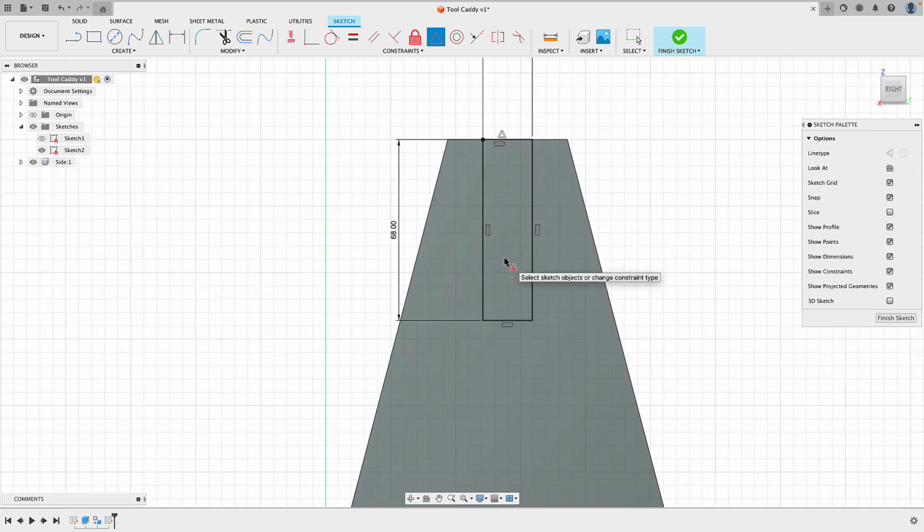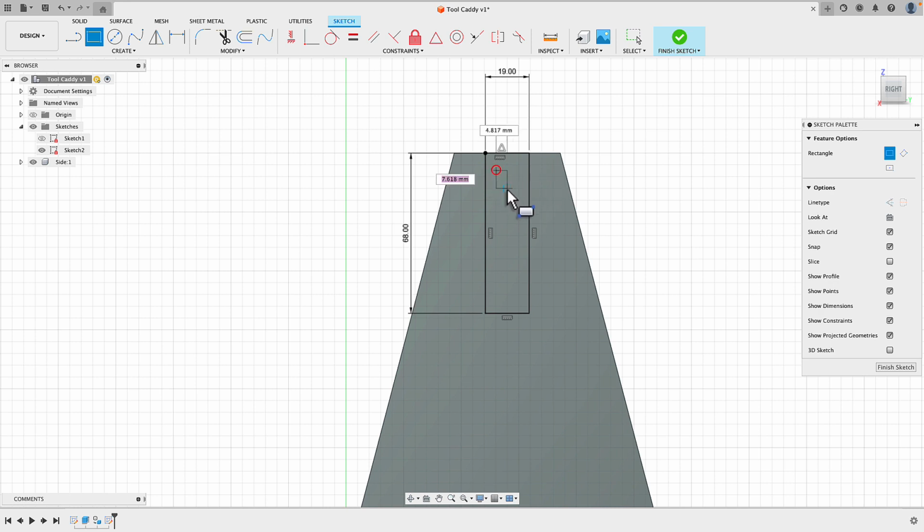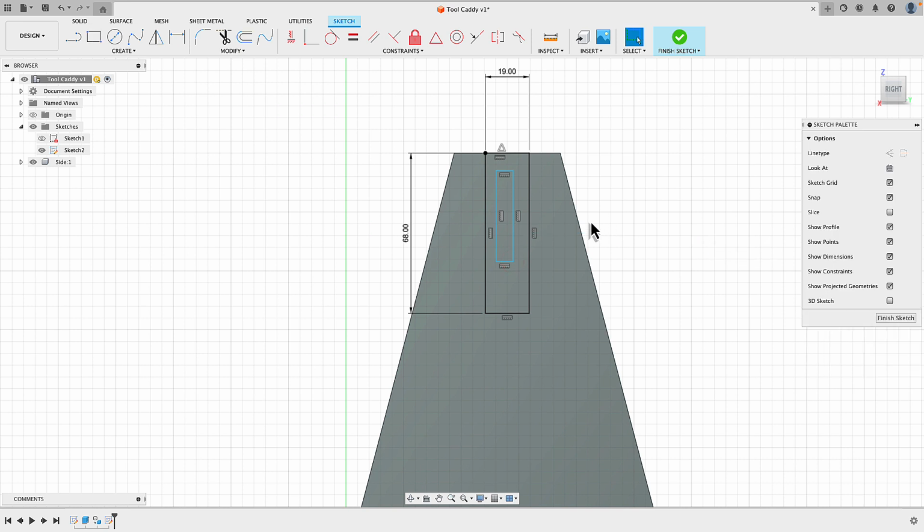Okay, we'll zoom in. Now what we want to do is create the geometry for our tenon and mortise. So again, we're going to draw a rectangle, and at the moment it doesn't really matter where it is in there or what the dimensions are on it. Now we're going to set up some geometry for it. So dimension, the first one I want to make is the thickness of it, 10 millimeters.